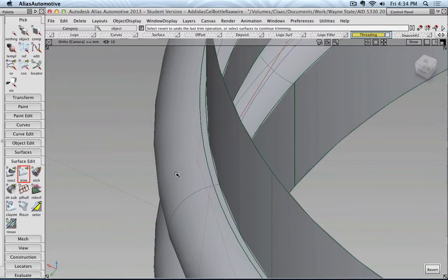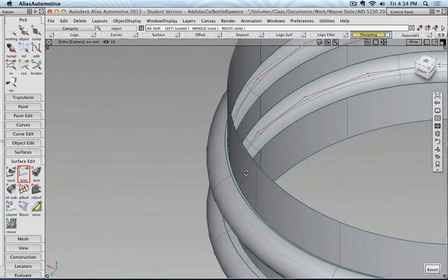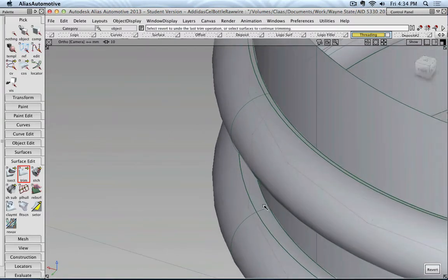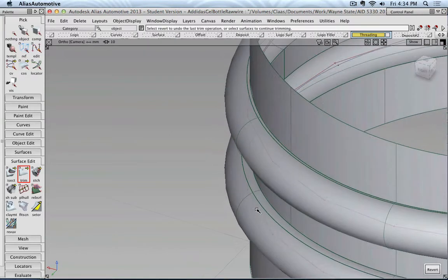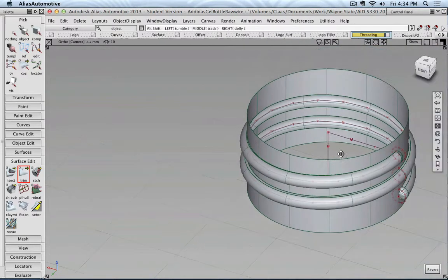green line. If I would have selected the outside, I would have to click here and also in between here to prevent that this surface remains, and then because here's a surface edge, this small part would have been removed as well. So in case you end up with small gaps between your pipe and your surface, you have to click those surface parts, for example here as well, or just simply do it the way I did it, click the inside and then remove those.